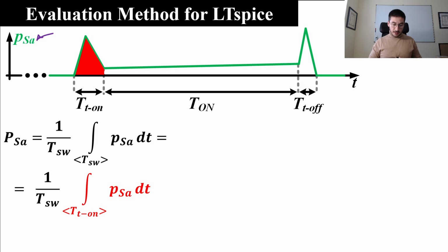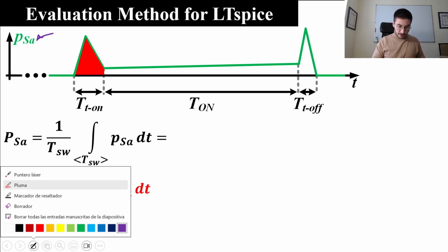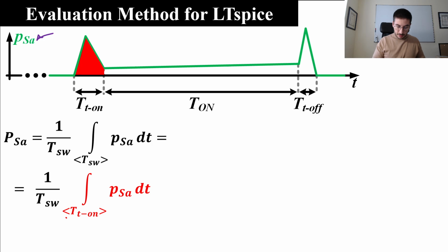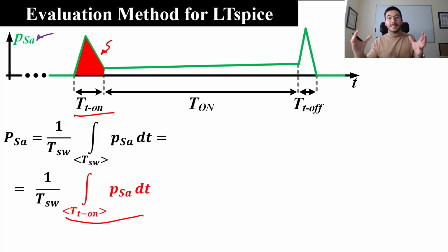In this way, we will have the first integral, which is evaluated in the turn-on interval in this part, and that integral is the integral of an instantaneous power. If we do the integral of an instantaneous power, we are evaluating an energy. So this is the turn-on energy.